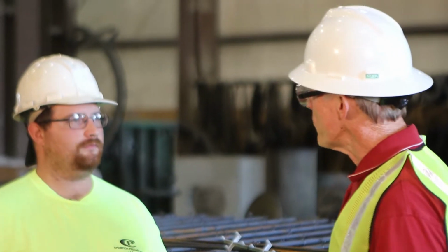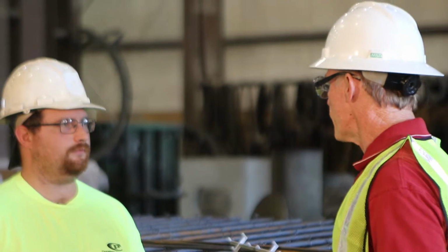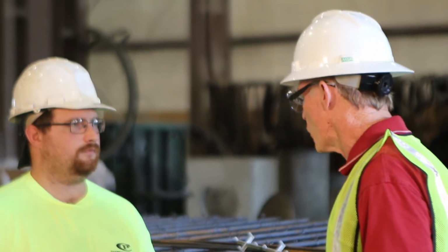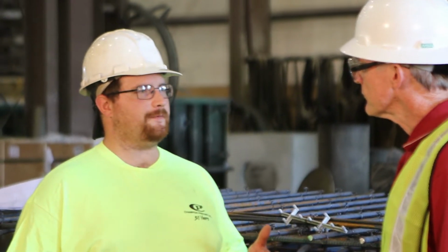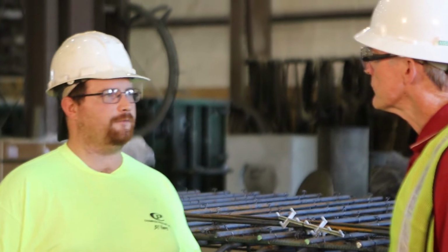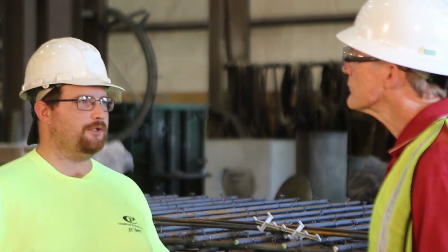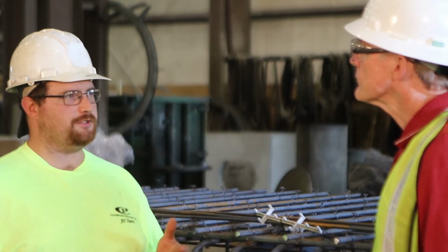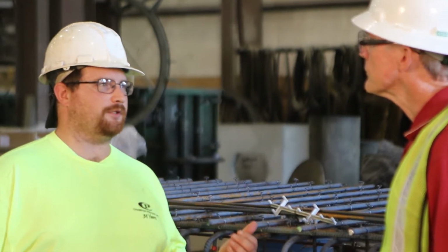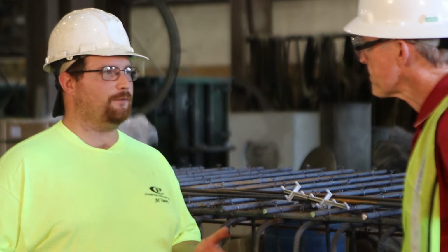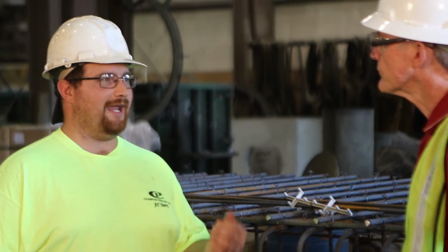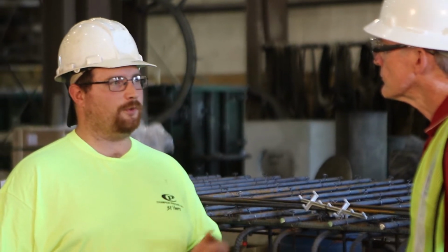So Michael, has there ever been a time when you didn't have the right reinforcing bar in your inventory and you had to make a substitution? Yes, and when this happens, we have a policy regarding reinforcement substitution. And when we do this, we have to let our QC department know, as well as on the production floor. Before we even do the substitution, we have to have approval from our QC department, and it is clearly written on our pre-pour report. That's an excellent policy.